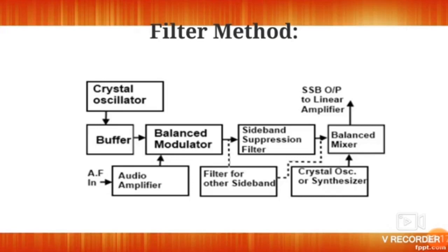Here the two sidebands carry the same information. The main drawback of the double sideband suppressed carrier modulated signal is that it has two sidebands, LSB and USB, and both carry the same information. So the same information is repeated. That's why any one of the sidebands is enough to know the information. Either LSB or USB is enough.